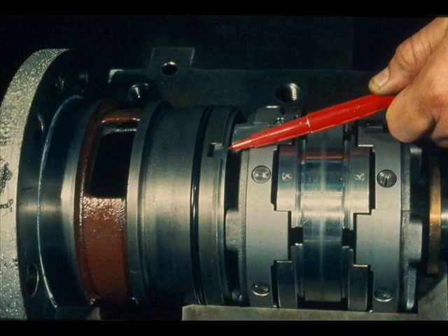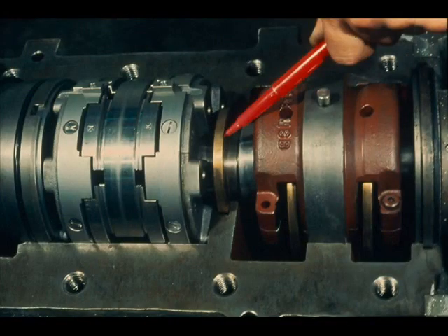The seal ring fits the shaft with very little clearance and prevents excess leakage of oil from the thrust bearing compartment and prevents air from entering the thrust bearing housing. Another bronze ring, identical with the one we just showed you, is recessed in this pump bracket and is retained by the shim pack. Its function is the same.